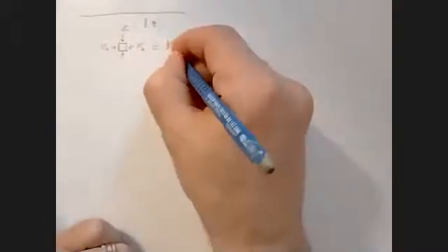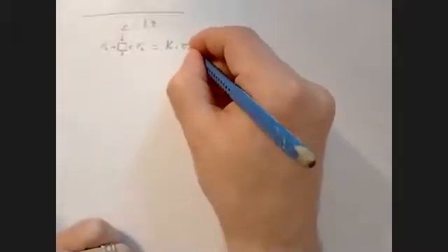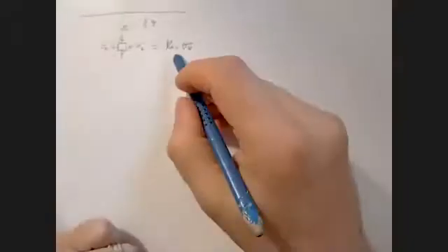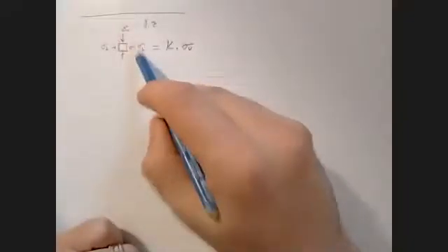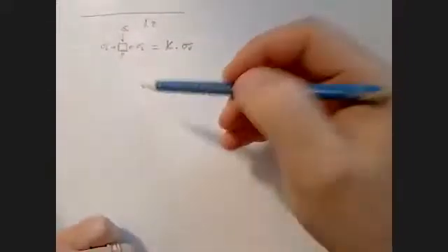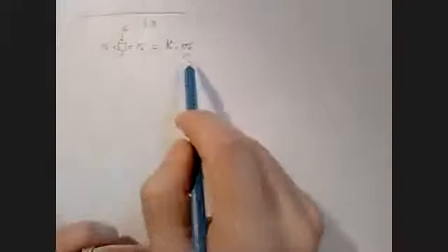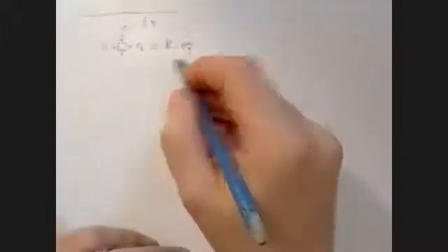So for horizontal stresses, we are going to say it is a fraction of the vertical stress. So again, it is in that sense kind of like a fluid pressure, but instead of being equal in all directions, horizontal stresses generally are less. In some rare cases, it can also be larger, so it is a multiple of or a fraction of the vertical stress.